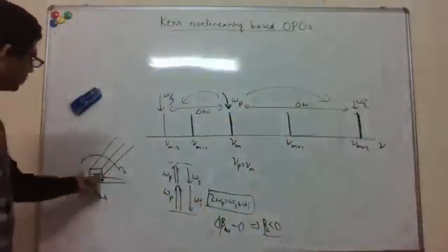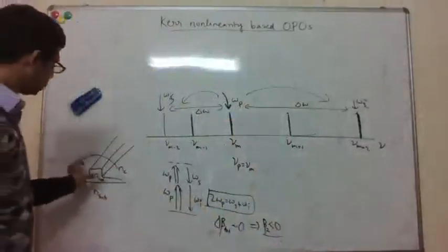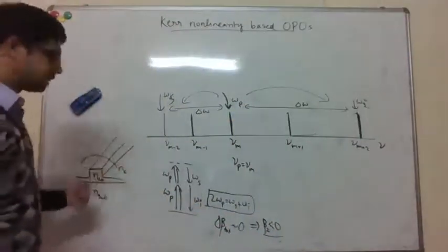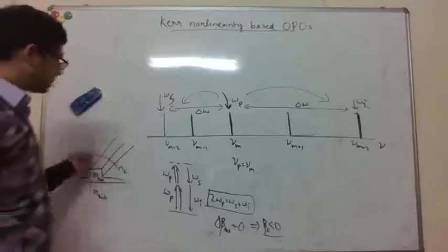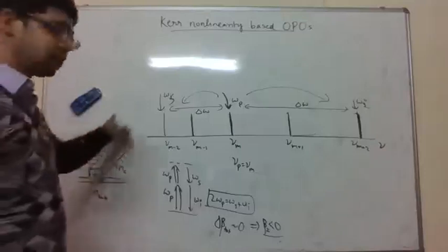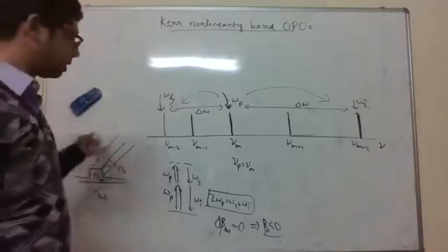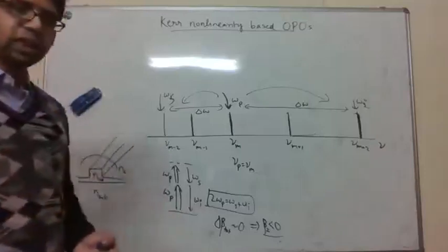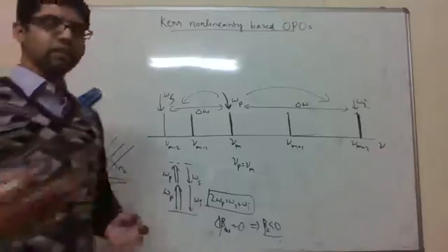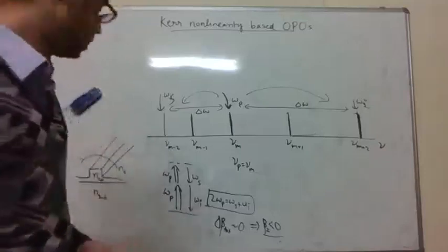Depending on the materials and the cross section you use, you have a waveguide with some dimensions, which decides the modes that are supported and propagate, which decides the n effective of those modes, which basically gives you the dispersion of the medium, right?